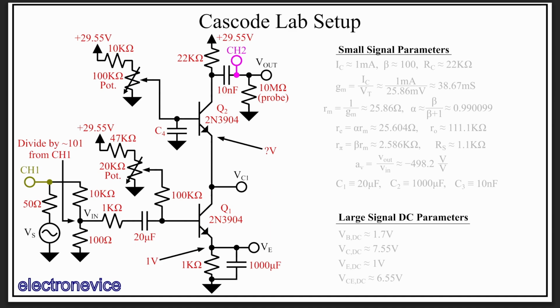First, we note that I've added another potentiometer plus resistors for the common base biasing network. The value of that upper resistance and the value of the pot itself are not very important, and just what I had on hand. What is important to note is that this biasing network does not need to be high impedance for our common base to work properly. In fact, we want the impedance from the base to ground to be as low as possible at our operating frequencies, which is why I've put this fourth capacitor, C4, there. We'll revisit C4 in a bit.